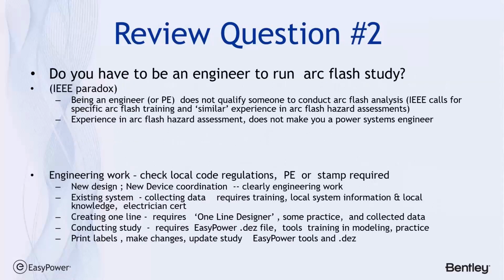The second question is, do you have to be an engineer to do an Arc Flash study? And my catchy little phrase for the day is what I call the IEEE paradox. And that is, being an engineer does not qualify someone to do an Arc Flash analysis. Basically, what's required is experience in doing arc assessments on similar power systems. And so making sure that someone has specific training and similar experience are mandatory.